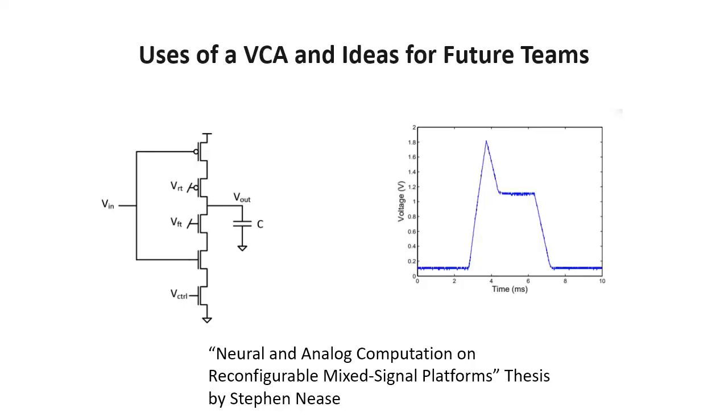While it's nice to be able to multiply sinusoids, the real utility of the VCA lies in its ability to create unique envelopes for sounds through multiplication. So I'd like to recommend that future teams take this design further by creating different envelopes for the VCA. One of the most useful envelopes that they could use is the ADSR, or Attack, Decay, Sustain, Release, which is produced by the circuit on the left.